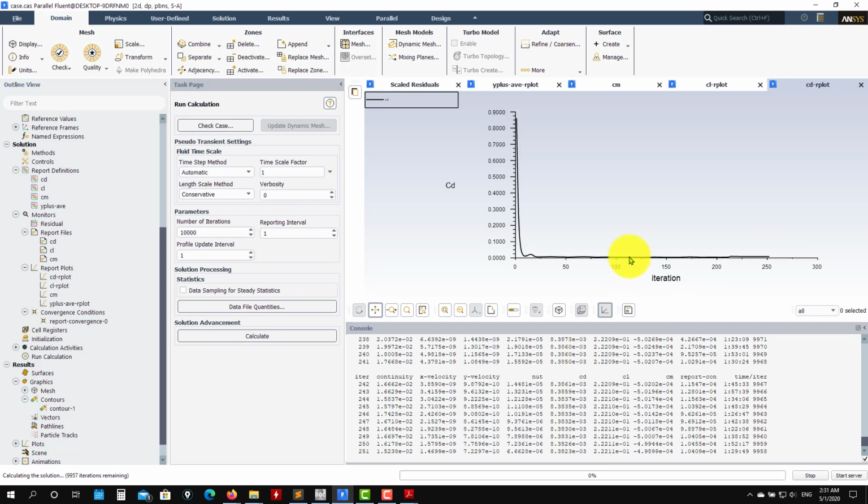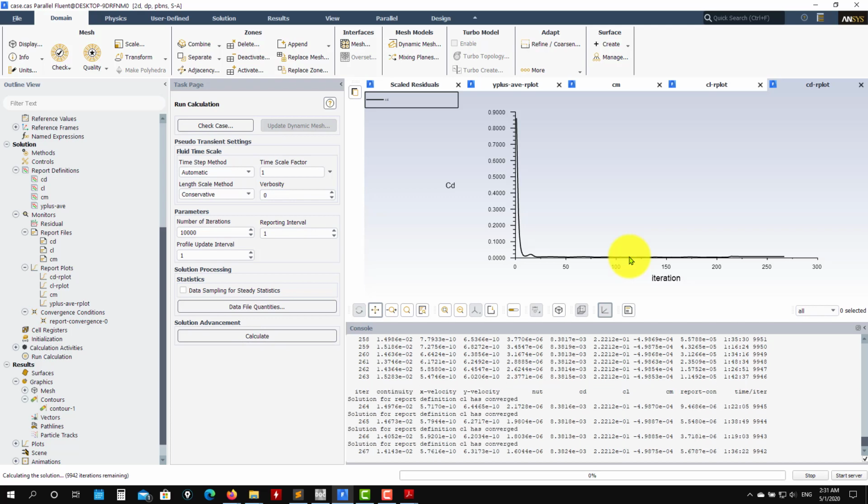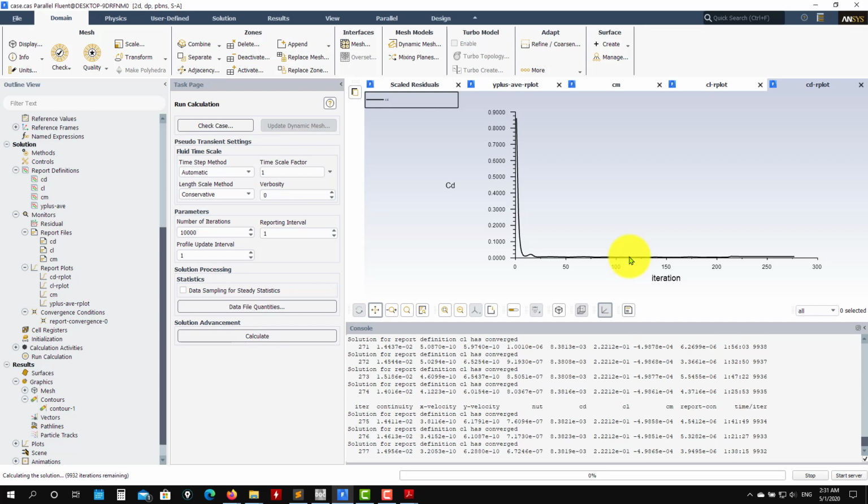This is what turbulence models are doing. They model that additional quantity that we saw when we derived our RANS equation, the mu T, the molecular viscosity plus the turbulent viscosity, that effective viscosity that we compute with the turbulence modeling. And clearly in this case you see that effect.